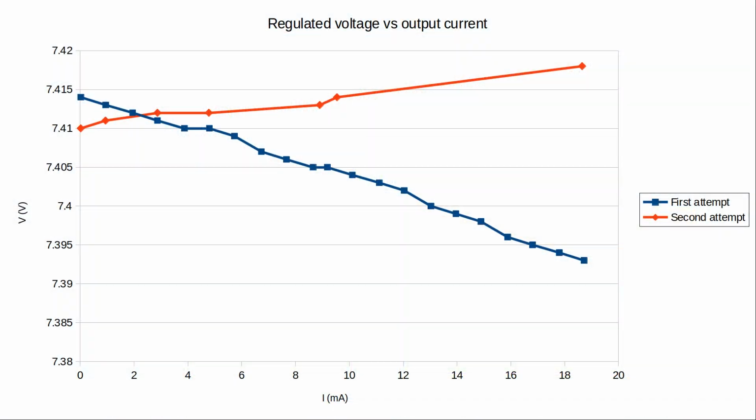Plotting that out, the droop is replaced with a little bit of climb. The voltage is still off. I could just decide to accept that, but one reason I want a clean, stable voltage reference is for VCO control voltages, and those are sensitive. A 1% error is something that a musician will hear as being out of tune. So let's take a quick look at the sources of error.